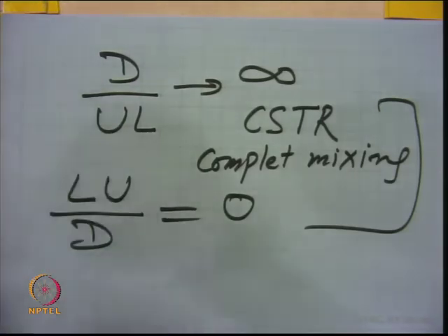It means you should have high superficial velocity, right. The gas velocity to the bed should be high, and the height of the bed should be high, make a larger bed height, right. So, these are the things which need to be checked when you do the study in a catalytic reactor and look at the kinetics, right.